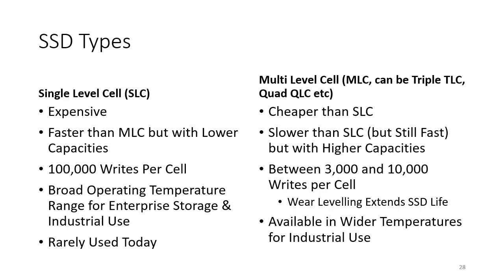Now there is a restriction that you can't get as many writes to the cells, so they have a shorter life. It's maybe an order of magnitude or two in terms of the number of writes per cell, maybe between 3,000 and 10,000 writes per cell, depending on the MLC technology. But because it's an electronic device, you would have a controller chip that wears out the SSD evenly rather than writing to the same cell each time. So although you might only get, say, 3,000 writes per cell, you would typically have a high capacity SSD, higher than you need, and inside the SSD the vendors already fit an even higher capacity still, that they don't report, so there's actually more memory inside that you're not aware of.